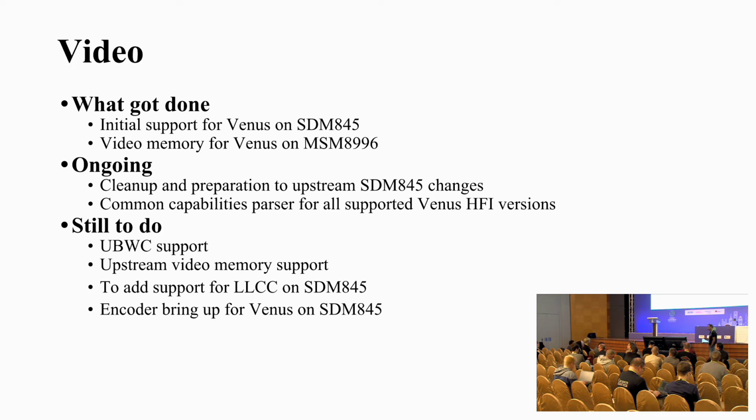Since it has its own mapping requirements, the firmware actually starts executing at 0x0, and you load the firmware into a particular reserved physical memory, and you need to create that mapping. Since it's an ARM core, the firmware needs to execute from 0x0, so it needs some custom IOVA mappings.